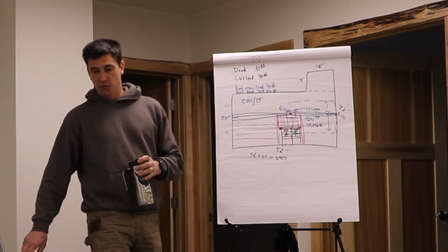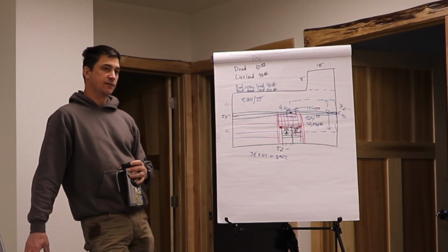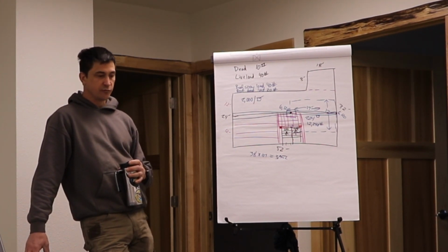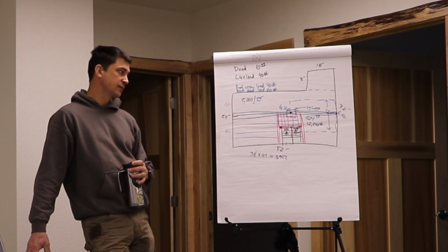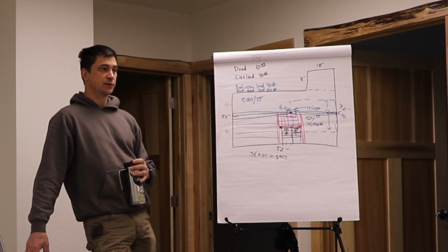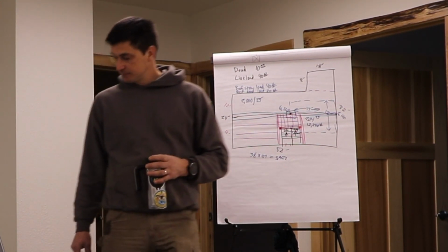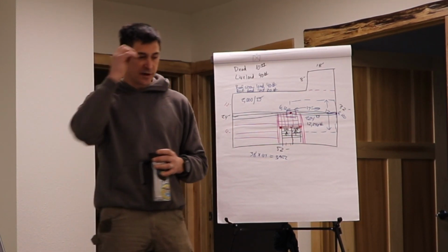Okay, well then we're going to have to go in the attic. Is there enough room in the truss for that? No. Do you have room in the walls where we can run ductwork down to heat the main floor and all the way down to the basement? These are the questions you have to start figuring out. And okay, then our floor plan's gone.